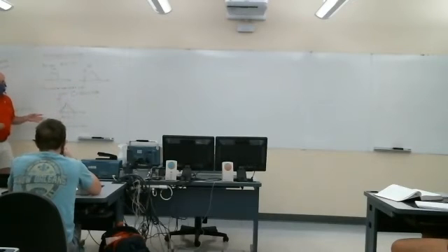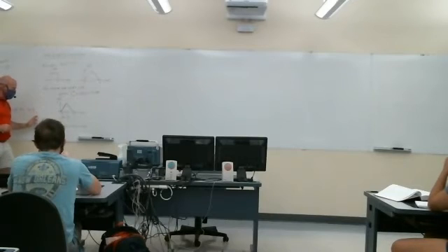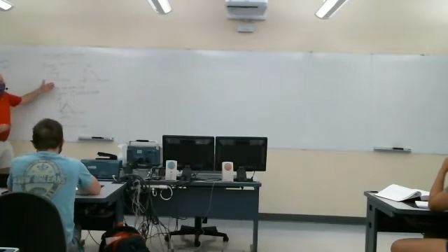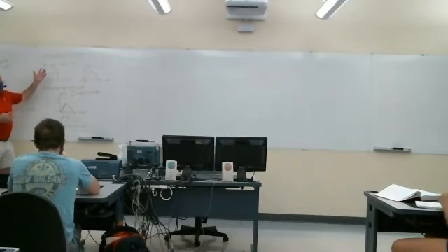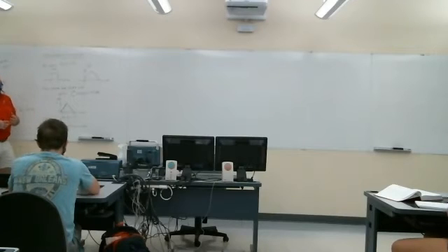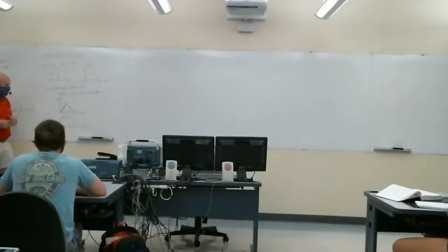But now what I have to do when I'm evaluating this integral is evaluate this for all possible values of t. So what this thing is doing as a function of t, as t is increasing, this block is sliding across here. I have to evaluate this at t equal minus 10, at t equal minus 8, t equal 12, t equal 1,000, all possible values. I have to draw that picture, but there are just some special cases that we look for. I can't do that for all possible values of t between minus infinity and infinity.